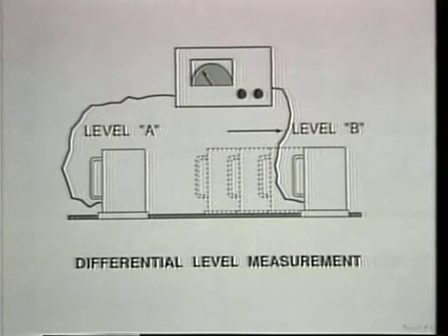Ideally, the surface being mapped should remain in its original orientation without any changes in tilt during the measurement procedure. However, some applications do not allow this condition to be met. In those cases, a differential level system can be used. Such a system consists of two levels and a single console. Both levels are placed on the measurement surface. Level A remains stationary, while level B is moved along the measurement path. The console displays the difference between the tilt of the two levels. With two levels, the effect of the tilting surface will be canceled, and the output voltage will represent only the measurement path tilt from level B.